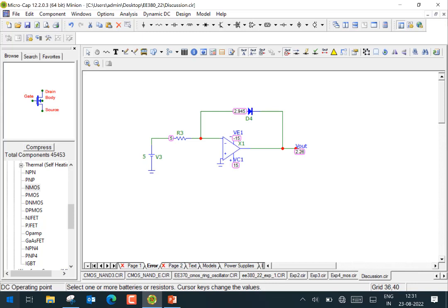And the other thing is, if the circuit were to function properly, if you take an op-amp and you have negative feedback, then this point should be virtual ground. Virtual ground meaning experimentally, if you try and measure, it would be a very low value. On an oscilloscope, it would be difficult to measure. This value is 2.9 volts. It's a very high positive voltage. So we checked here and this is also a large positive voltage.